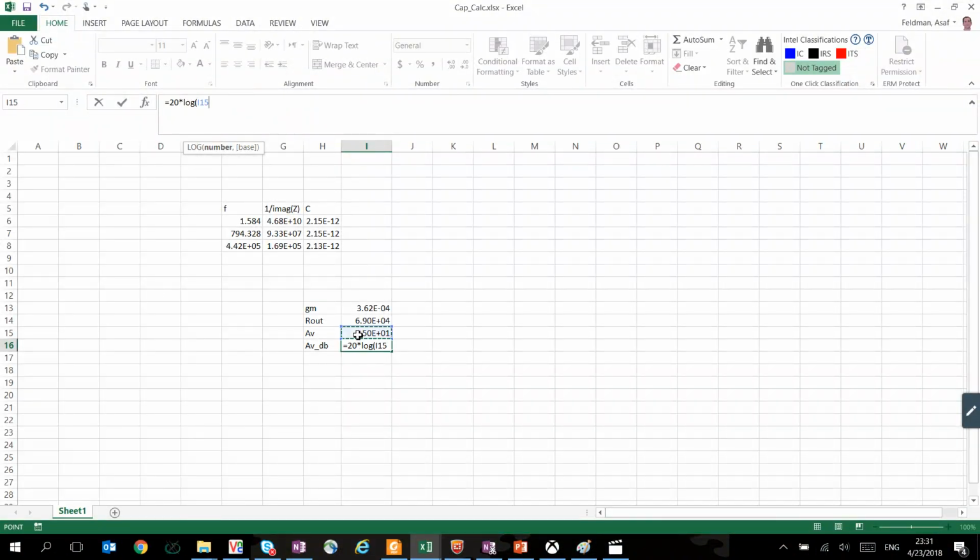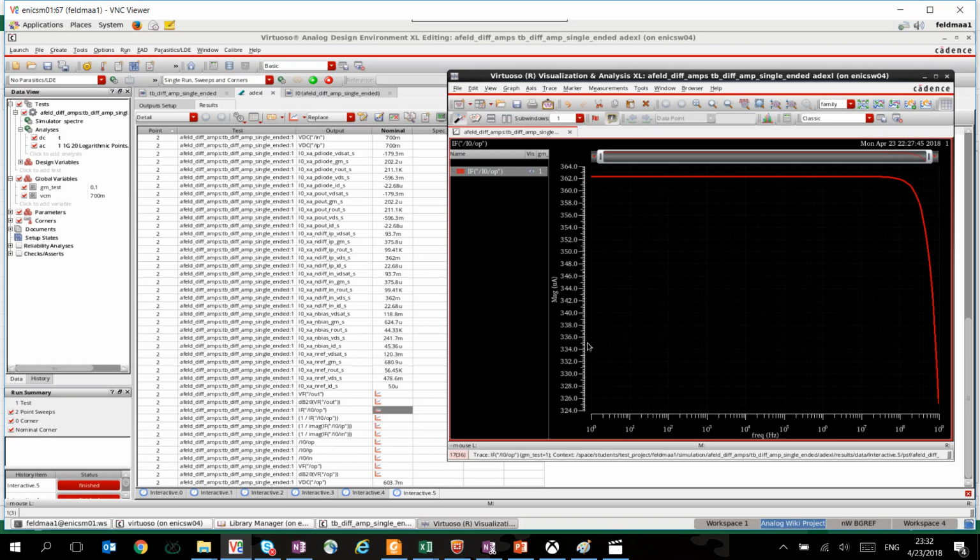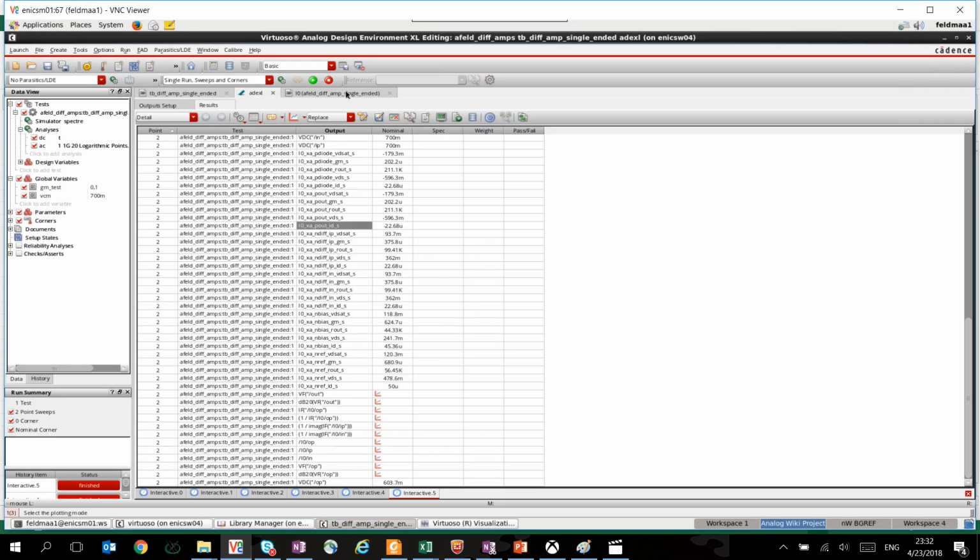Of this guy. So what are we going to get? Look at that, 28 dB. So we see that our parameters, GM and R out, are correct. The way we measure them is correct. So we see that we could extract the parameters from the box without even knowing what's in the box. That's very helpful when we try to evaluate this box.